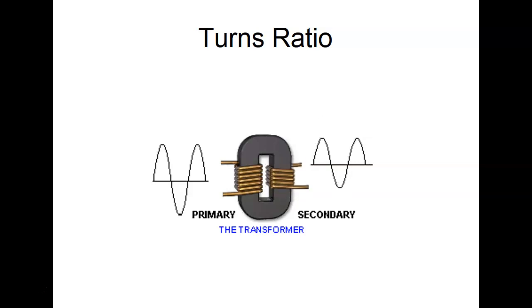We can have multiple windings, and we can change the turns ratio by the way we connect the windings on the transformer. But as far as us setting what we want, we can't do that. So we have a divide by 4, divide by 2. What we have is jumpers that we can put on it to change the turns ratio on either the primary or the secondary.